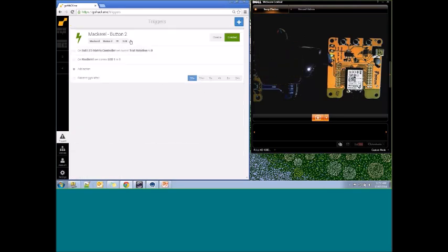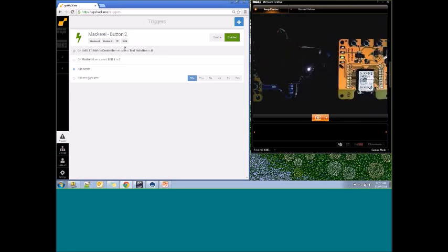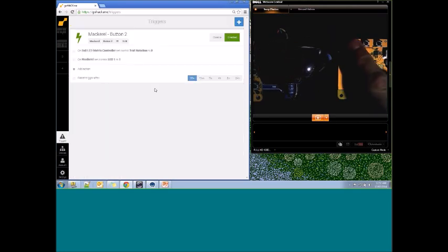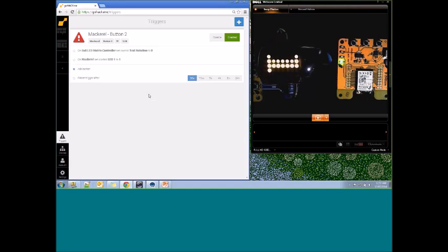So now, if I press the button, we should see, let's pull that across a bit more so you can actually see it. I'll turn off this guy to 0 so that it's not impeding the demo there. If I press button 2 now, we should actually see the LED go on and you'll see the text fire. So that's impacted 2 devices. You've now pressed one button and it's turned the LED on the macro board and also changed the text direction on the LCD demo.